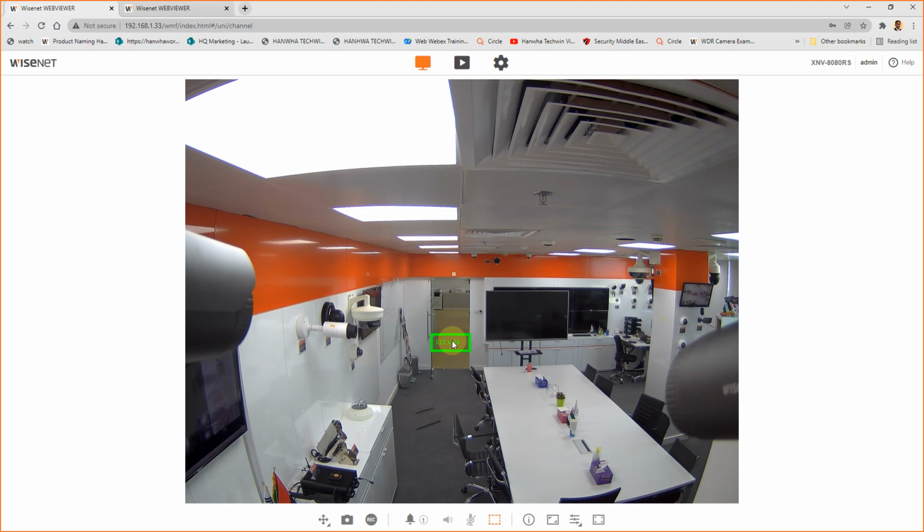You have to only look at the first number, H by V, horizontal. Left to right is horizontal, 110 pixels per meter. I'm only getting 110, not enough to get identification. Even for recognition, not good, because 125 is the minimum for recognition. Some people say 100, some say 125, but roughly speaking, this is just a bare minimum even for recognition.